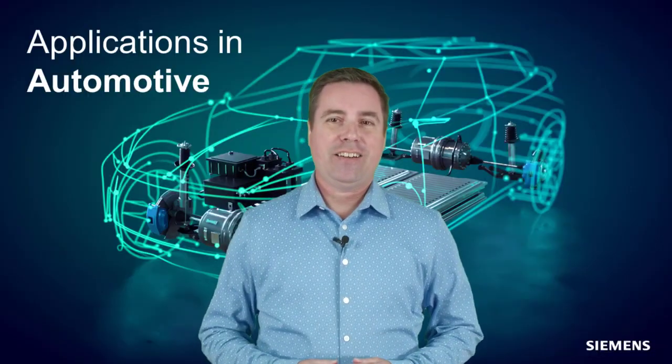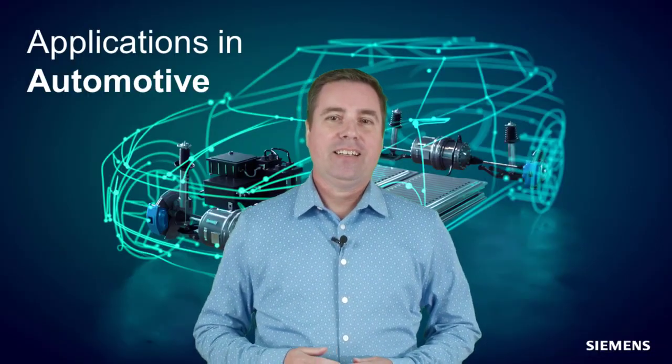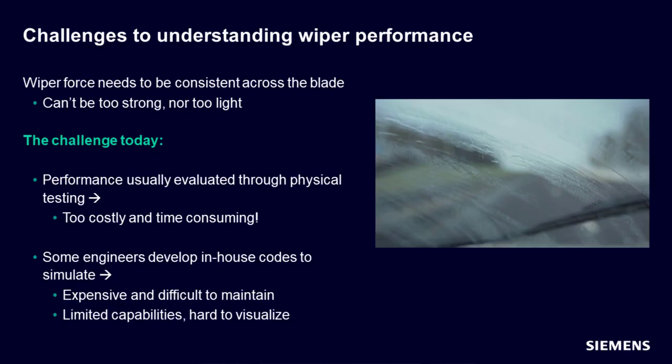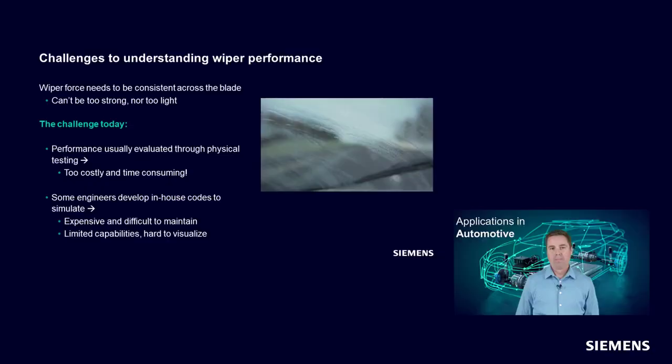Another interesting engineering challenge in the auto industry is the performance of windshield wipers. A good performing wiper blade needs to have a consistent load as much as possible as it moves across the curved surface of a windshield. But the load can't be too light, nor can it be too strong. Inconsistency in the loading will leave streaks that the driver needs to peer through.